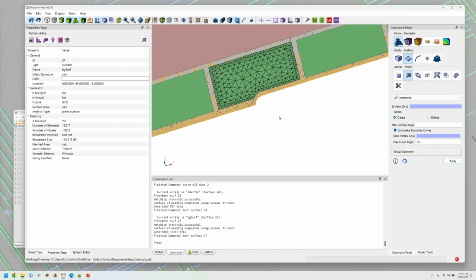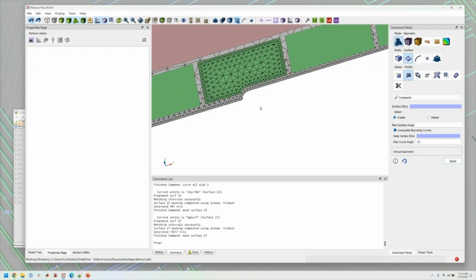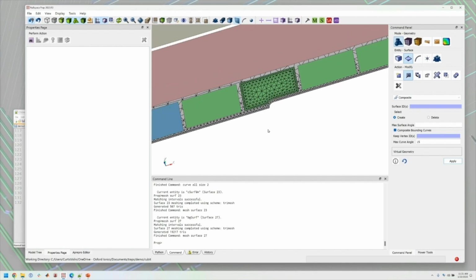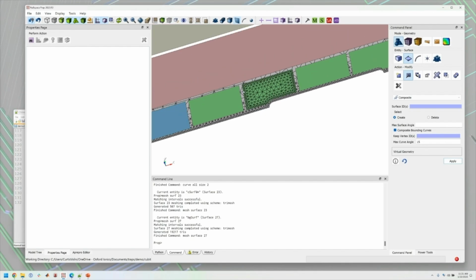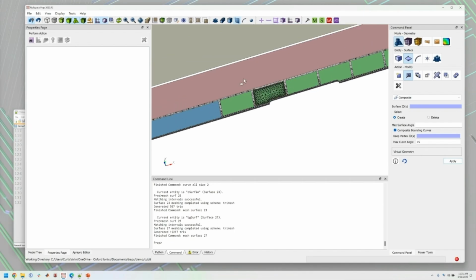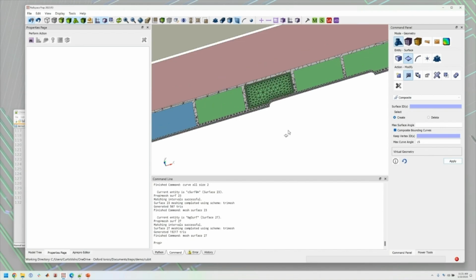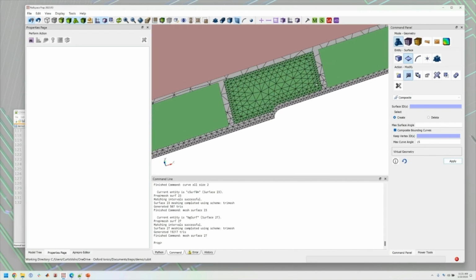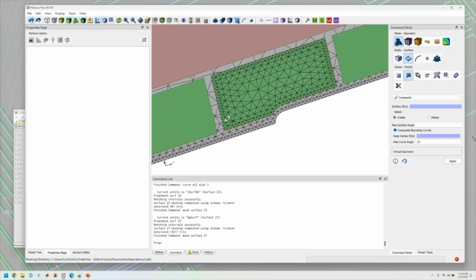So now is when it's good to have just a little bit of insight into what Nullspace is doing when it solves the model, right? For each electrode, it applies 1 volt to this electrode in simulation while keeping all of the other electrodes grounded. And then it calculates the charge distribution on each of these triangles, assuming a uniform distribution on each triangle that's consistent with that 1 volt of potential.